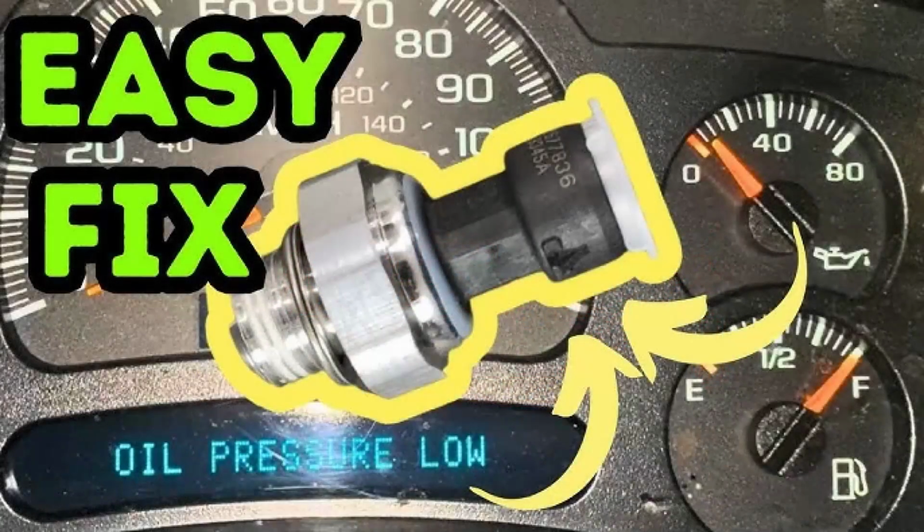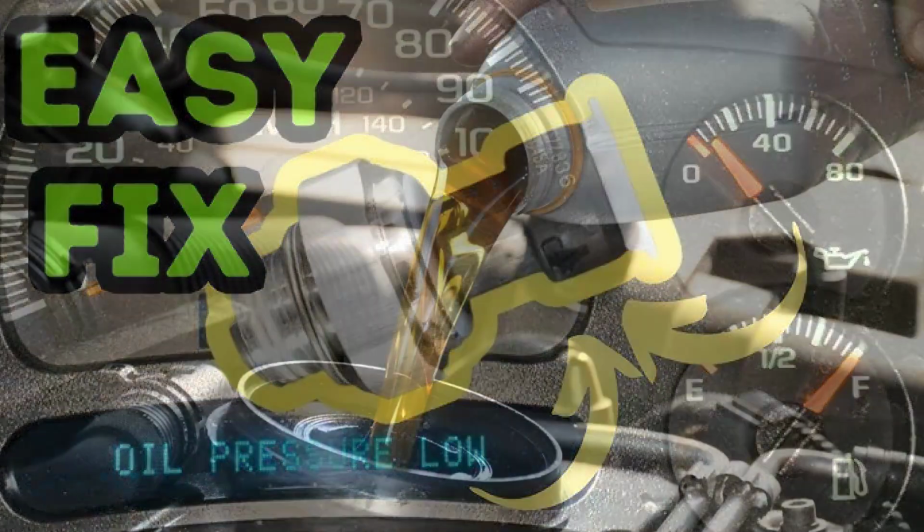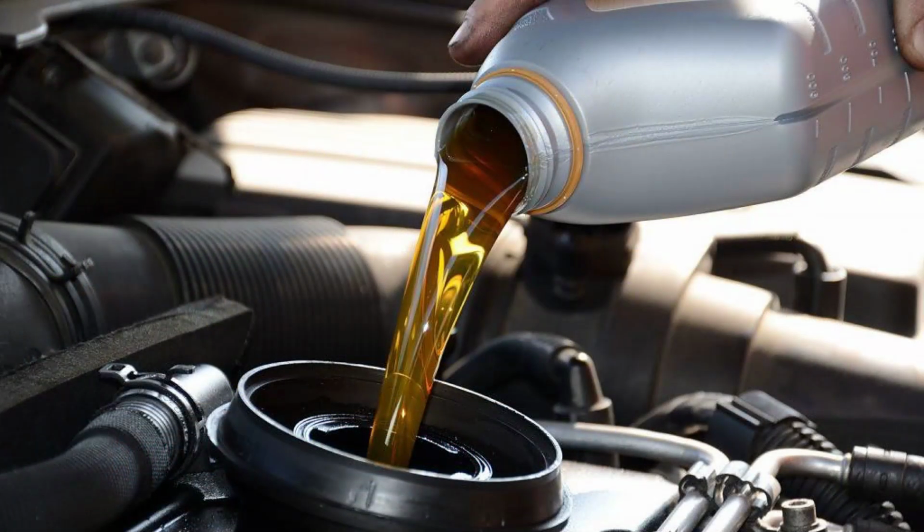The repair for the P0522 code depends on the underlying cause. Here are some potential solutions. Top up the oil level. If the oil level is low, simply adding more oil may resolve the issue. Repair or replace wiring. If the wiring or connectors are damaged, they will need to be repaired or replaced. Replace the oil pressure sensor. If the sensor is faulty, it will need to be replaced with a new one. Repair or replace the oil pump. If the oil pump is malfunctioning, it will need to be repaired or replaced.